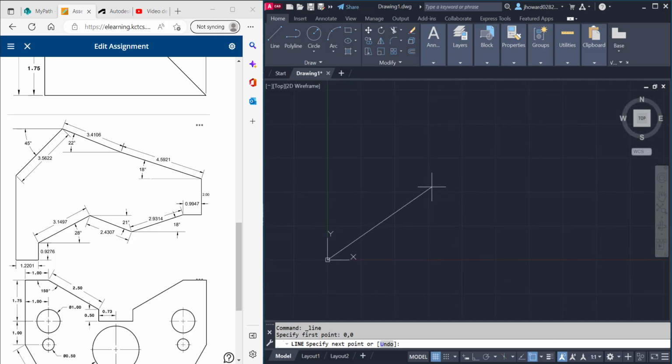If I'm wanting to put a certain angle in there, now remember, when we start out, we were setting up our drawing. Remember, we put our 0 going due east, and it goes counterclockwise all the way back around. Well, what's going on is this is 0 going this direction, straight up's 90, due west is 180, and going south is 270, back around to 360 to 0, right?